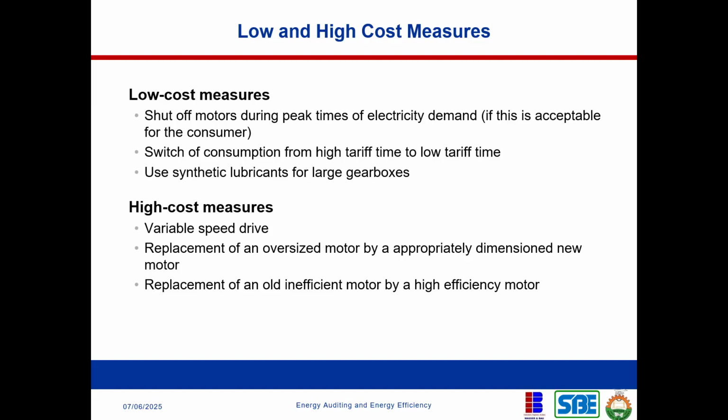It's important as an energy auditor to also understand the tariff structure of your client. How are they being charged? Is there a time of use? Of course, in Nigeria, we don't have time of use, but that does not mean that it may not come at some point. But imagine that you go to other countries and there is a time of use tariff. So it's always good to look at the tariff structure and then advise based on when some of the motors should be running. That is, if the production process can be variable, then you can make this recommendation. Use synthetic lubricants for large gearboxes. Now, these are low cost measures, right?